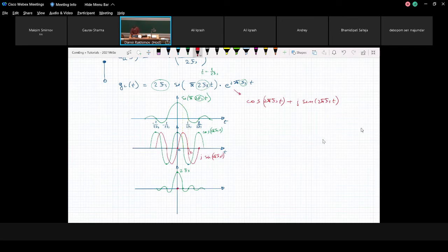Then at 1 over 4 fs, sine as amplitude equals 1. Then you multiply with some positive amplitude corresponding to the psi function. You will have something like this. And then you just need to take care about the sign of your resulting signal. In the range from 1 over 4 fs to 1 over 2 fs, you have positive sine with positive psi function.